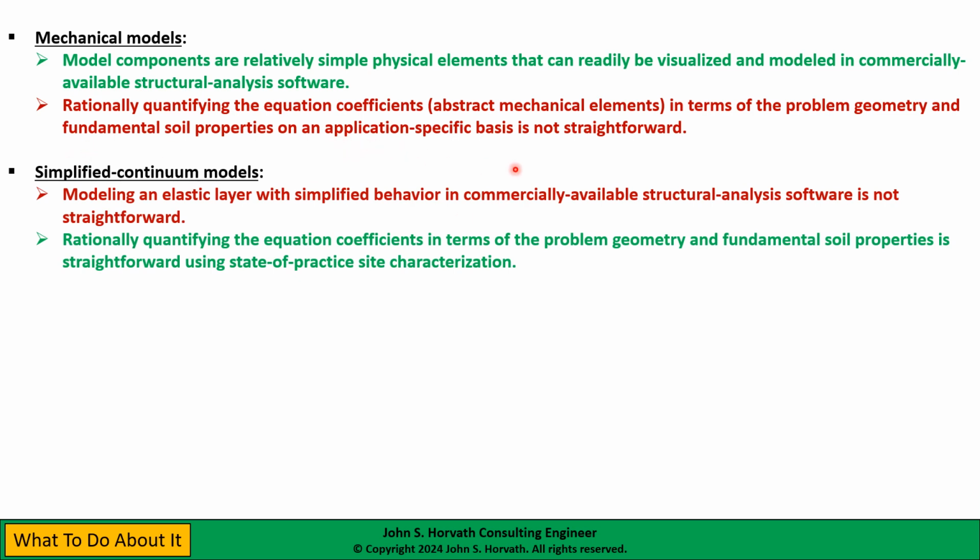Now, if we look at simplified continuum models, their negative or con side is the fact that modeling an elastic layer with simplified behavior in structural analysis software is not straightforward. On the plus side, for the coefficients in a multi-parameter model developed by the simplified continuum technique, it's fairly straightforward to come up with the values from problem geometry and fundamental soil properties from state of practice site characterization. So the point I'm getting at here is that